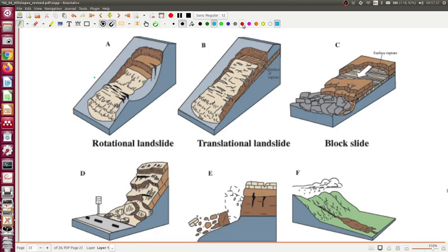One of them, here I'm going to use red for this failure color. So one of them is having a scarp that causes a rotational failure like this, and that's because we have this free surface up here. And so, if this fault were to continue going straight down there, it would just go deeper and deeper into the earth, and then nothing would move, right? It's going to hit this point at which you're just deep in the bedrock. And so in order for this material to move, this fault surface ends up scooping up towards the Earth's surface and creating a rotational landslide.